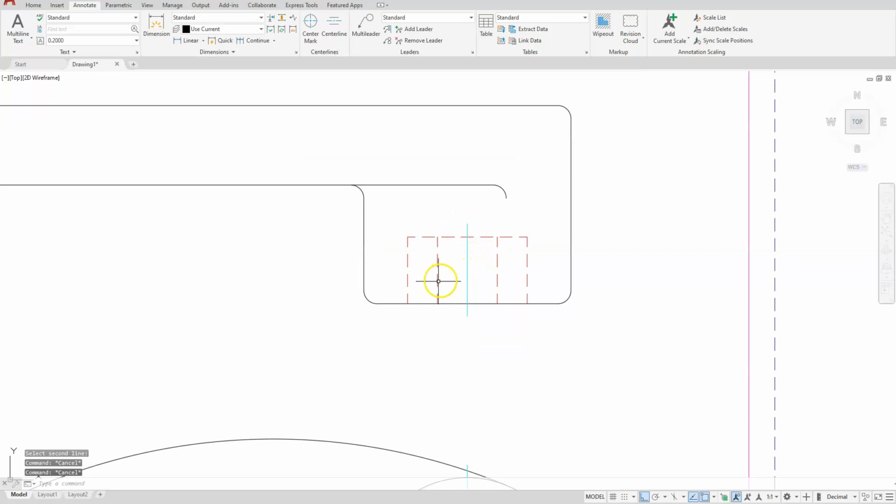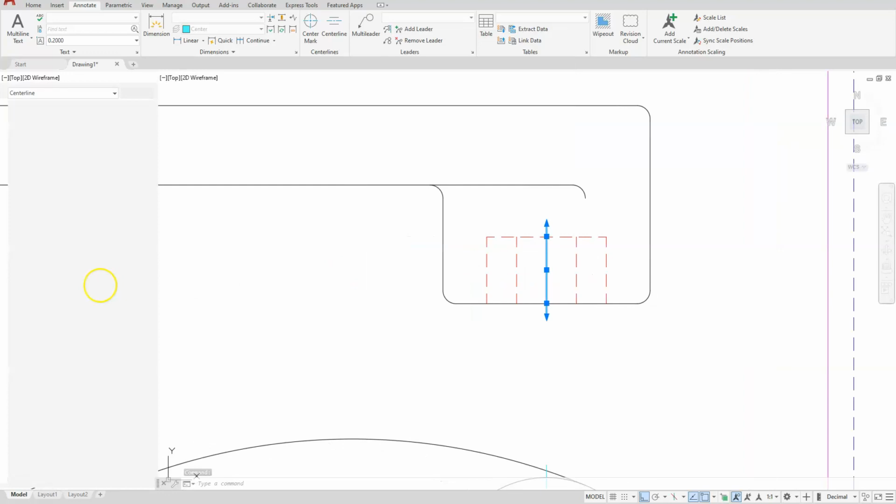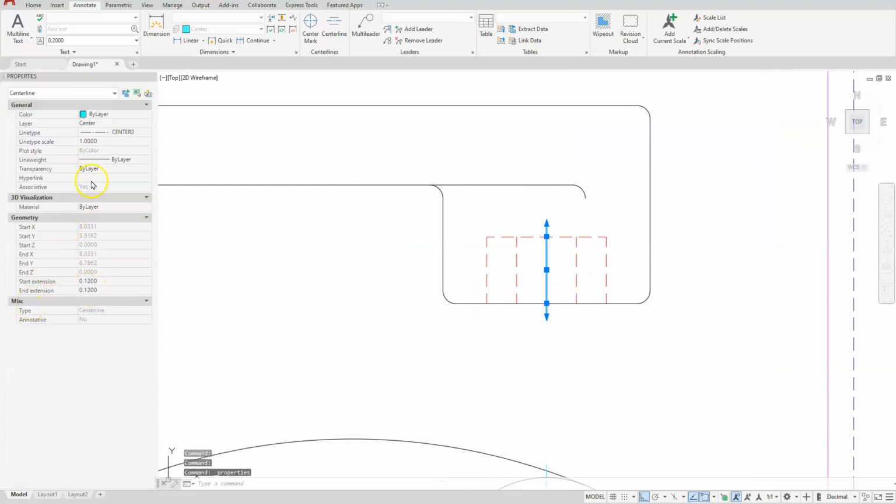You can see that that's not giving me that line in between it, or it's not looking like a true center line. So select it and go to Properties. I just did a right click on that and went to Properties. And I think I'm going to leave my Properties dialog box open from here on. Line type scale, let's go ahead and adjust that and make it 0.5.